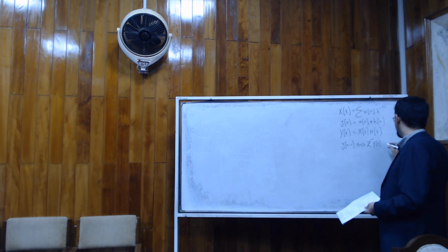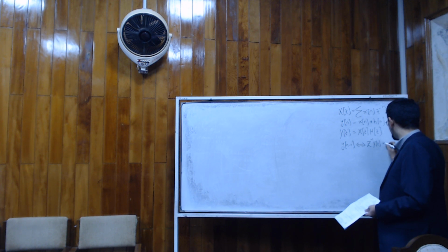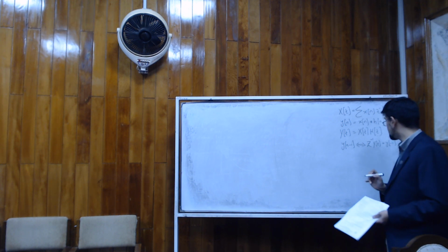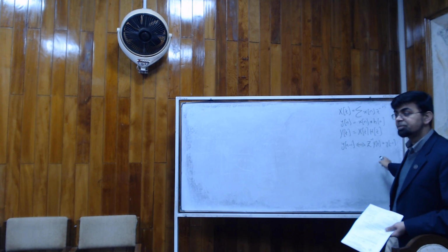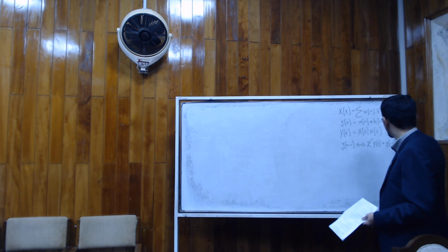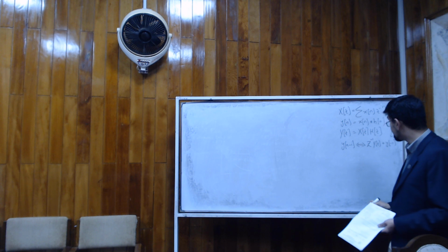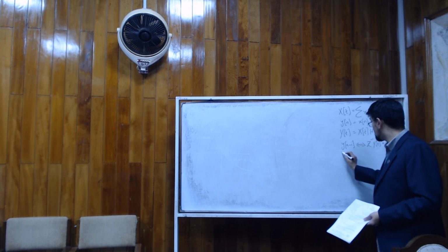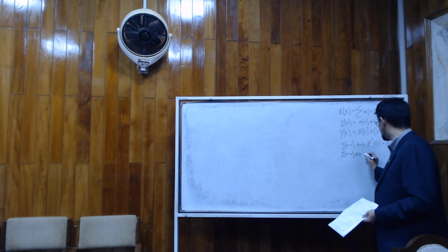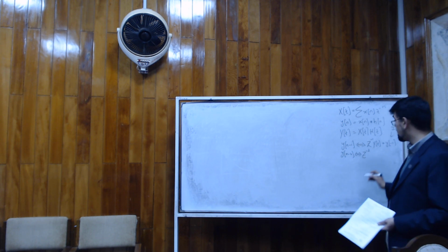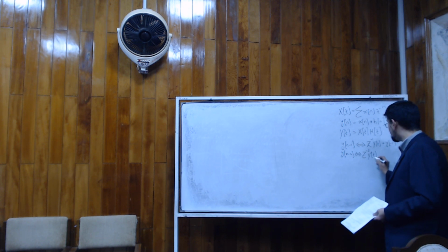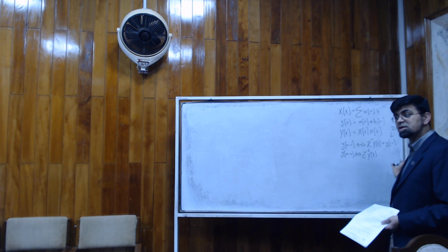Okay, so the initial condition formula goes, how does it go? It is z inverse Y(z) and then there is y[minus 1], small y in time. Okay, and this is the initial condition. What else? Let's say the same rule keeps on applying. I'll just show you the pattern. z to the minus 2, Y(z). We normally write up to here. We skip the initial condition as being 0.